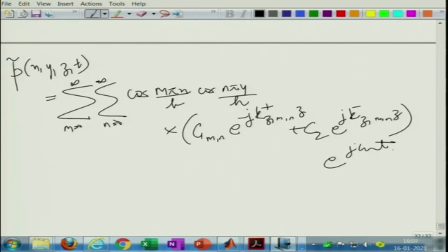it's fairly more mathematically involved, and what we probably do is directly get on with the conversion of the Laplacian into cylindrical polar coordinates, and then get to the variable separation form, and probably not get into the derivation of the Bessel function, which invariably comes up when you deal with circular cylindrical geometries in almost all physical problems. Then our solutions will proceed and things will become very interesting, because most of our mufflers are circular in shape in cross section. So, it is important to understand that. Of course, there are some variations also.